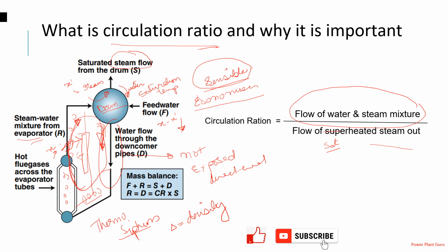So what will happen here? There will be a lot of steam generation, and once the steam generation is up to the nucleate boiling range, it is good. It is good that it will happen, and then your water-steam conversion efficiency is high, and you are making a good quantity of steam. But after this, once there is a departure from nucleate boiling,